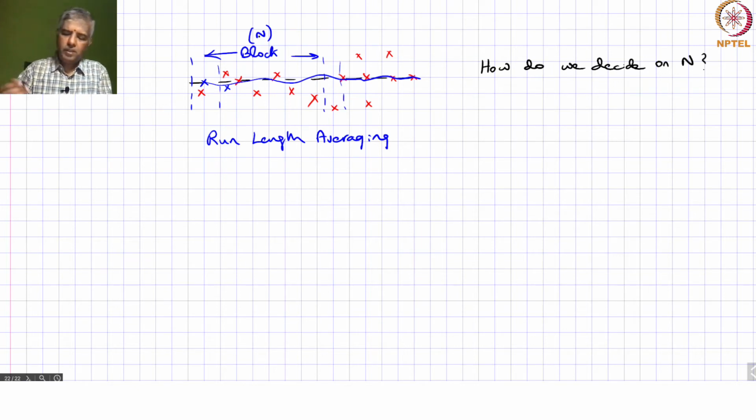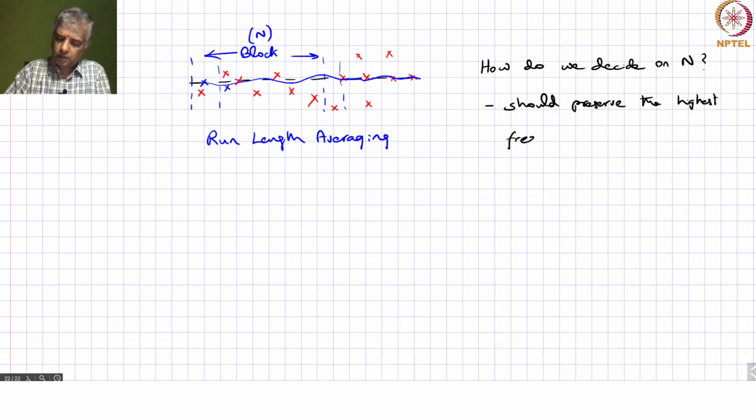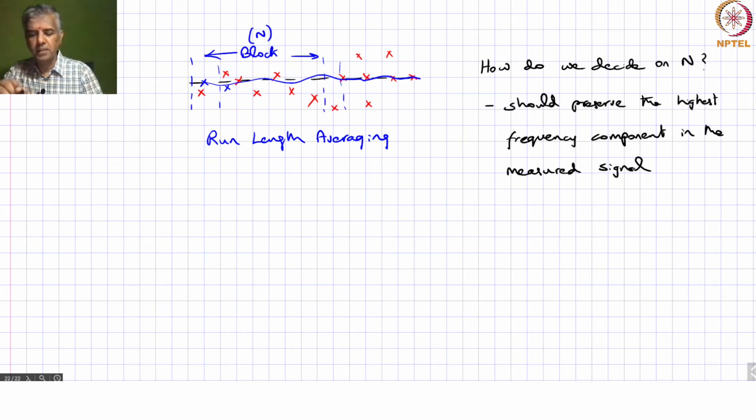Well, in general, the principle that you want to keep is that your processed data should preserve the highest frequency component in the measured signal. Okay, it should preserve the highest frequency component in the measured signal.